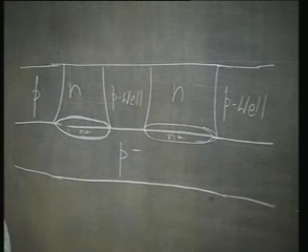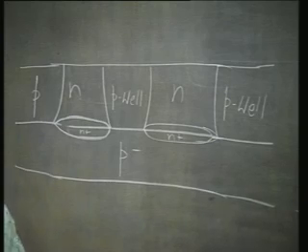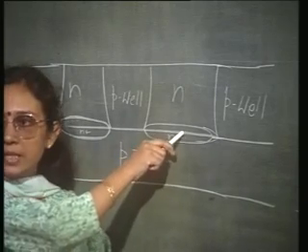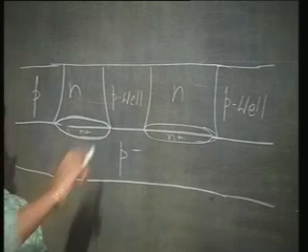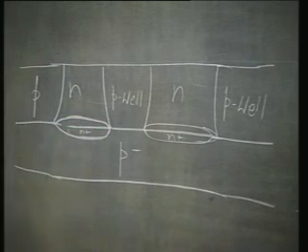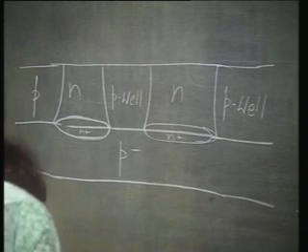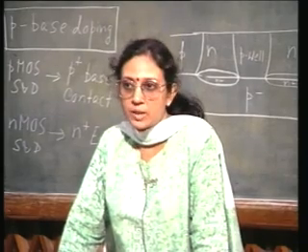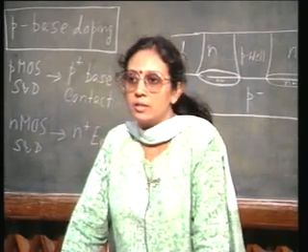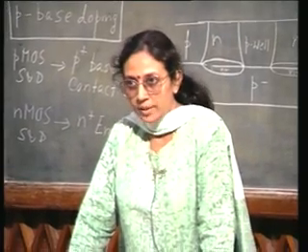So, even though I have actually added two steps, one of the buried layer and the other of the epitaxy, this is in fact, if you remember, your retrograde well with epitaxy, which can be used both to prevent the latch up in CMOS as well as to cut down the collector resistance in bipolar junction transistor. Okay.